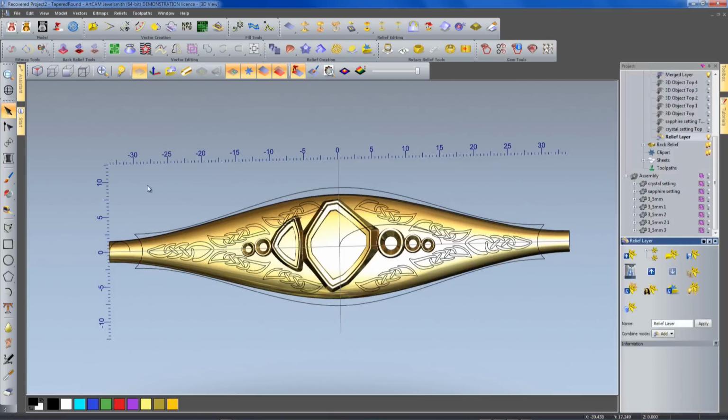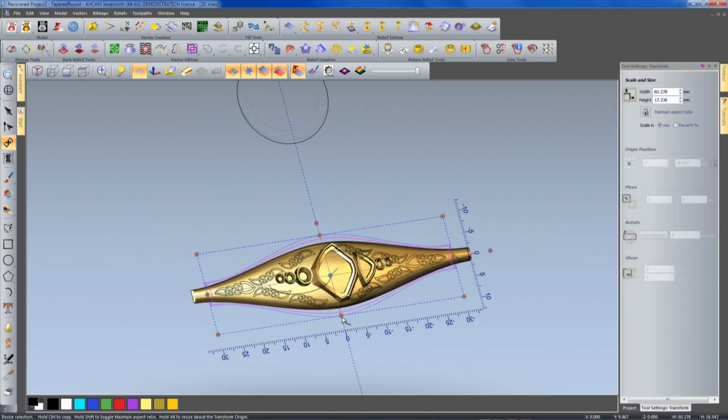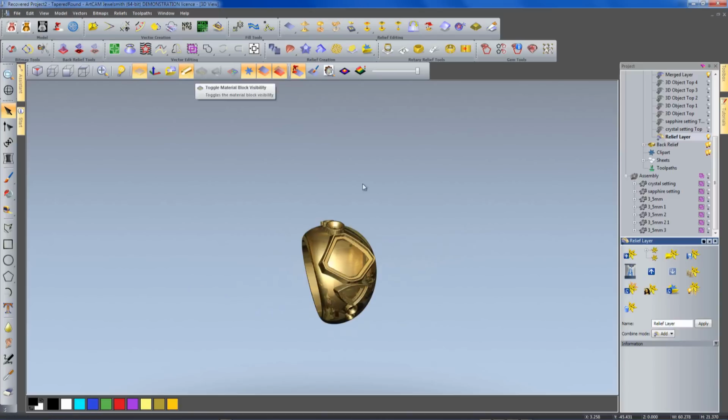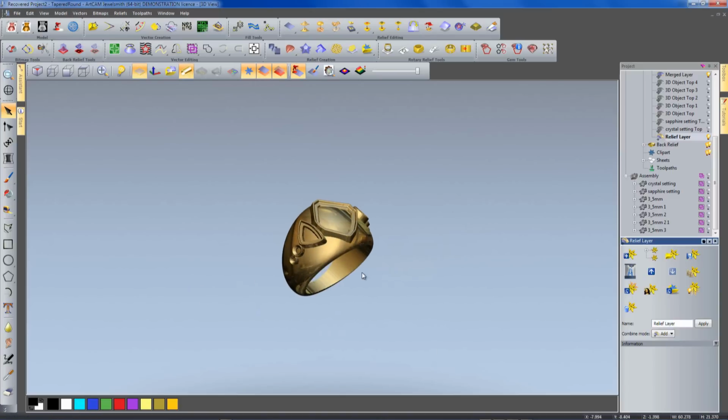Okay, I just need to extend this outside vector just a tad more so it's away from that ring, so it's away from the main body of the ring. And on this we're going to use the vectors in a reverse action really to get the shape. So most times you're going to be looking at just forming those shapes onto the surface, but this time we're going to use them as the mandrel for forming the outer part of these shapes. So we're going to select all the motifs, control and group those, and I'm going to use the outer one too. Turn off the vectors, wrap it into the ring form again.